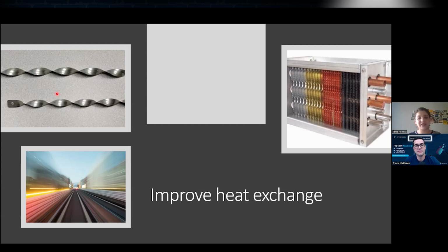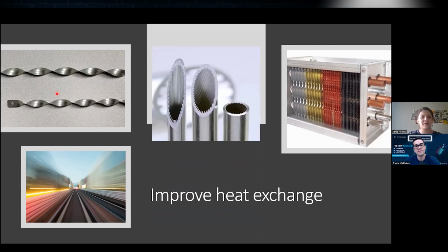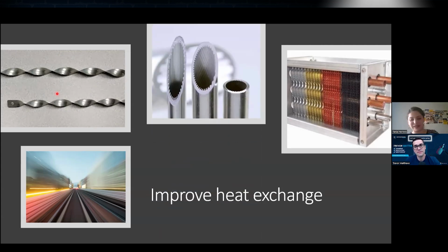So yes, it's increasing the velocity. This one is the one that I wanted to talk to you about before, when I was talking about the liquid flowing through the wall of the piping. Some heat exchanger manufacturers have these special tubes that have a grooved surface.